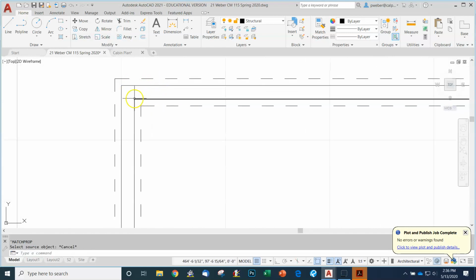Now let's do something else over here. Let me draw a line from here to here. And remember, we had a 2 foot 8 door. And I need 1 inch of space on both sides. It's 1/2 inch for jam material, 1/2 inch for shim material. So let me offset this line 2 foot 10 inches to the right. So I'll call up the offset command. And I'll type in 2 foot 10 inches, press enter, touch this line, throw it off to the side.